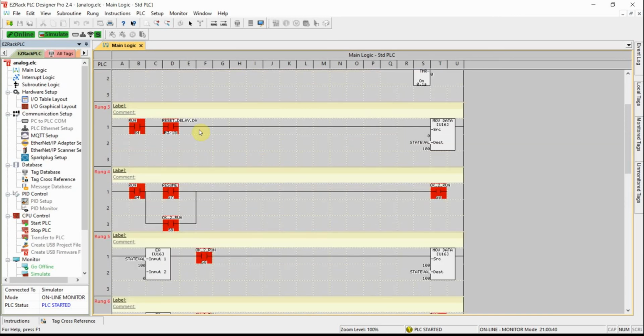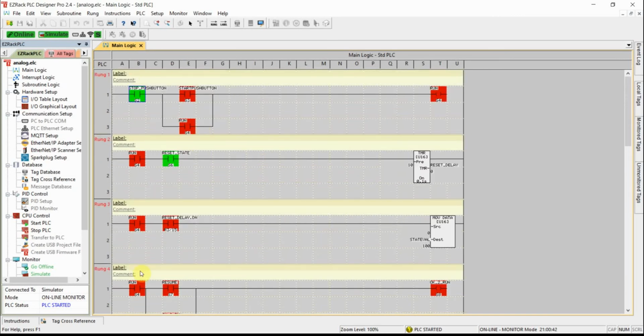It's very tempting even for me to just jump in. Like all this stuff right here, the start, stop, push button. I mean, you really should only activate that if you're in Power Up. But because now we don't automatically go back to 0 on the states, we don't want to put a state condition in front of it. This has to be live all the time. This one, you could say if you're not in state 0, I guess, but I think I would just leave it alone.